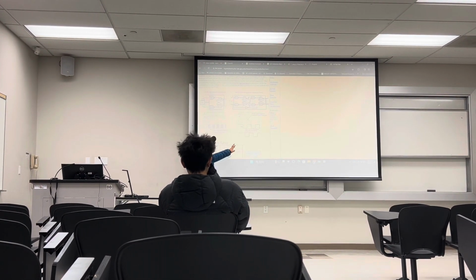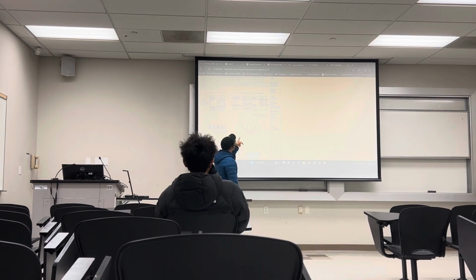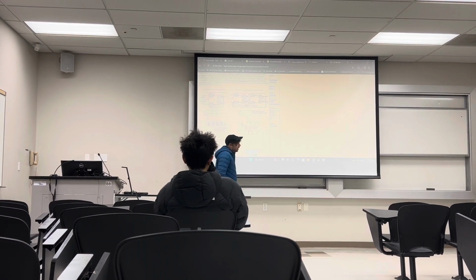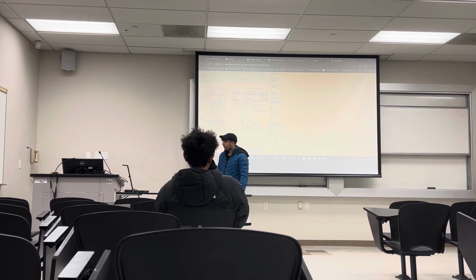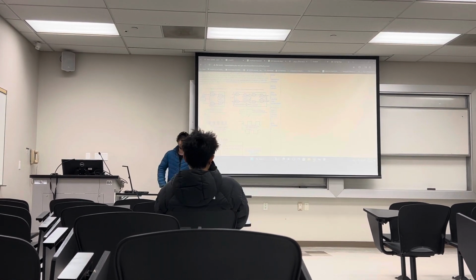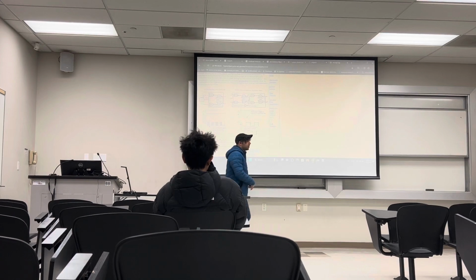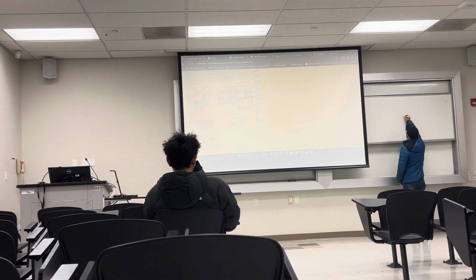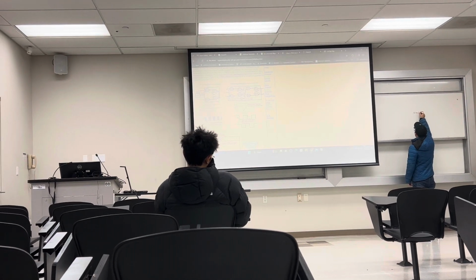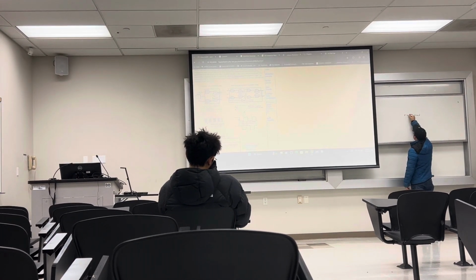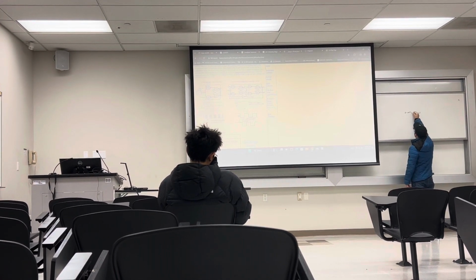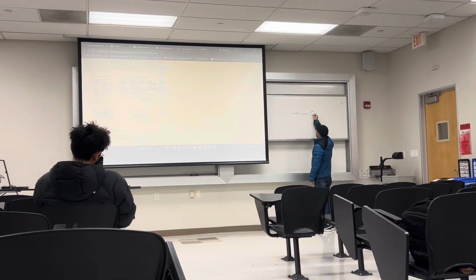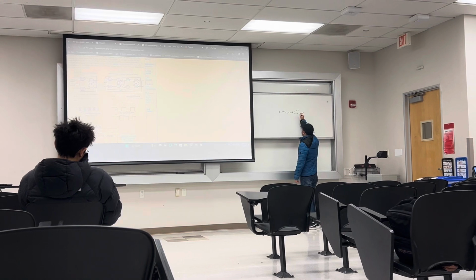So first, you need to design this JK flip-flop. As you will see, the JK flip-flop is built from NAND gates and NOT gates. As you know, for project 3, you designed the NAND gate. So go to the project 3 files. You have the NAND gate, the schematic, and also the layout. You don't need to change anything.